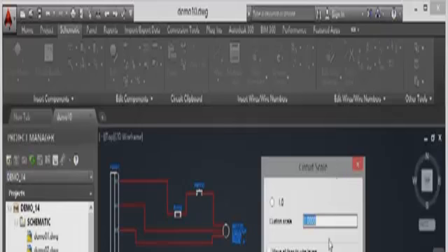Now what this allows me to do is put in a custom scale, which I don't really need to worry about because I made sure that the W block circuit used an inches scale. And because I'm using the JIC Imperial Standards, I know that it's going to be in inches again when it comes into this drawing, because this drawing is also in inches.